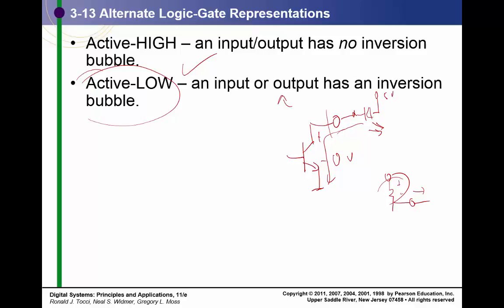Other cases here is that this is our input, and this is our push button. This is going to float high whenever that's there, and when I close the switch, that supplies the ground. So when I push the button, the input goes low.